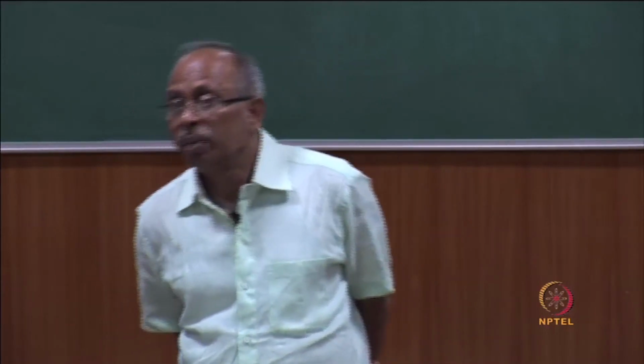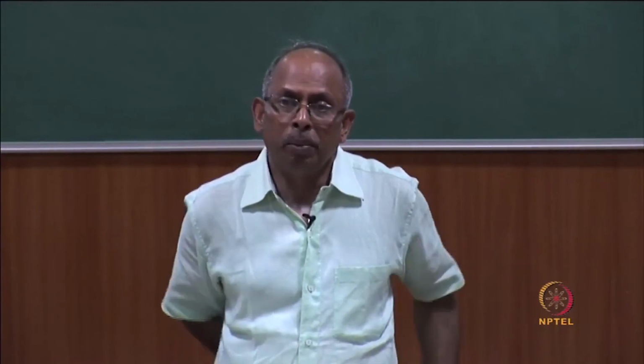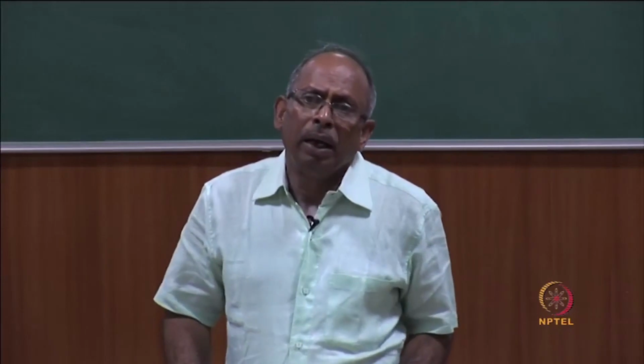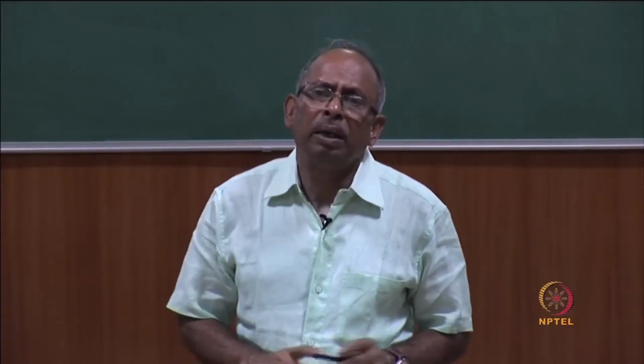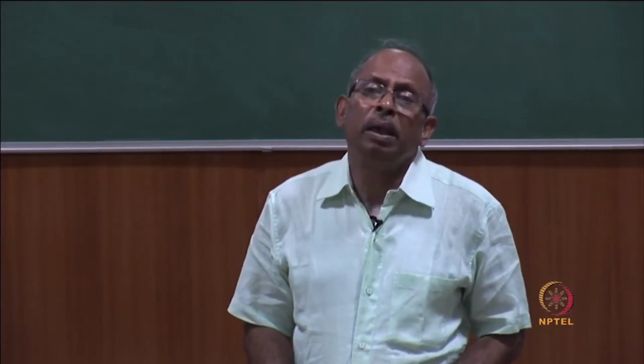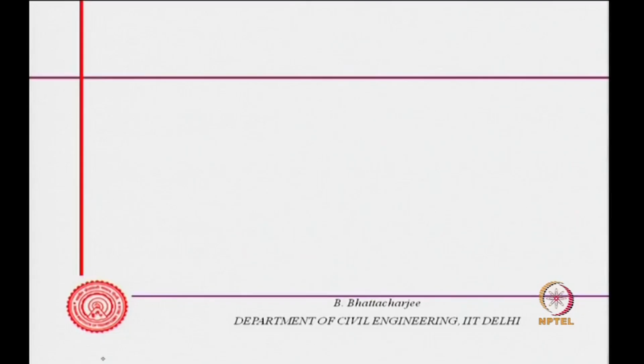So, drying shrinkage would occur at later stages, because of loss of water due to evaporation, and this can continue for months, 1 or 2 months in fact, and within 6 months, of course, by and large this will be complete. And this is one of the reasons for cracks in many thin sections. Right. So, let us see plastic shrinkage more.